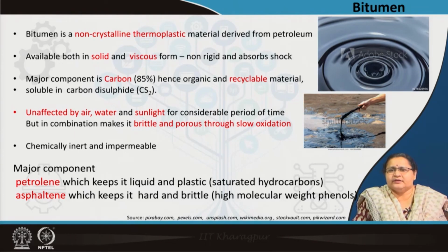It is soluble in carbon disulfide, that is CS2, and yes, it is a recyclable material. It is a very impervious material, it can be continuously used, it is weatherproof, it can sustain temperatures, it can sustain shocks. So, all the qualities we had discussed for a damp proof membrane are with bitumen, and hence it is extensively used.